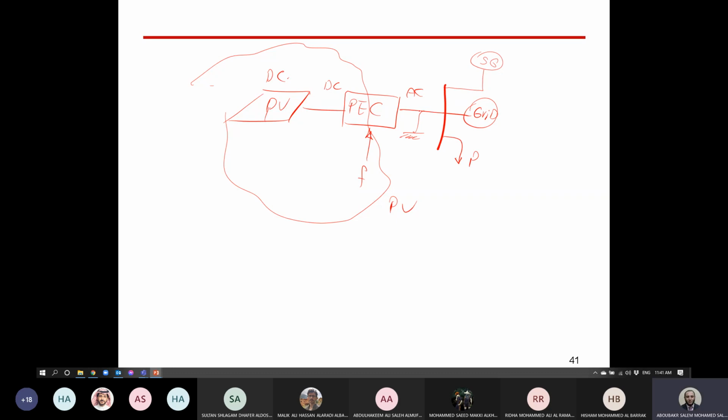What's the meaning of short circuit? Or what is the effect of short circuit? Short circuit means the load will be very high. Huge current. It will collect all of the surrounding power. You have current which should go to the grid here, or loads here and there and so on. However, this short circuit will collect all of these powers together. And due to the impedance of the short circuit, which is very, very small, almost zero impedance, the current will be theoretically infinity or very high. Right?